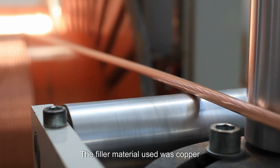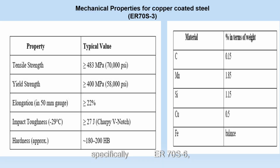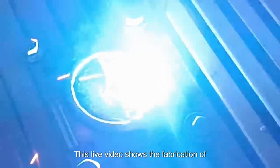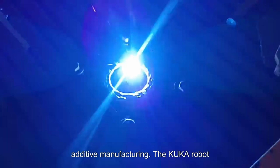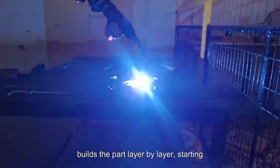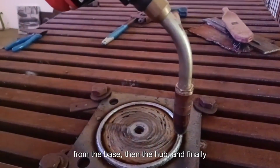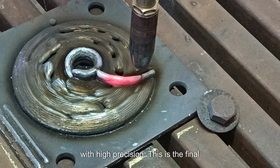The filler material used was copper-coated steel wire, specifically ER70S6. Chosen for its excellent arc stability, low spatter levels, and suitability for high deposition processes like WAM. This live video shows the fabrication of a radial flow impeller using wire arc additive manufacturing. The KUKA robot builds the part layer by layer, starting from the base, then the hub, and finally the blades, following the programmed path with high precision.